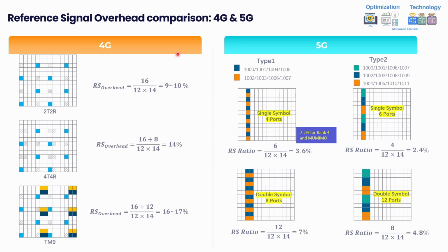If you remember in the table, I highlighted that 5G is no longer using the cell-specific reference signal. It's called cell-specific reference signal free, or CRS free. Because in 4G we used the cell-specific reference signal to estimate the channel condition.